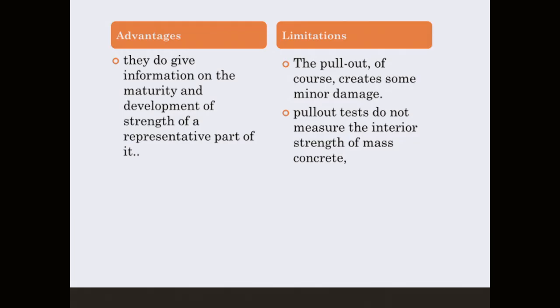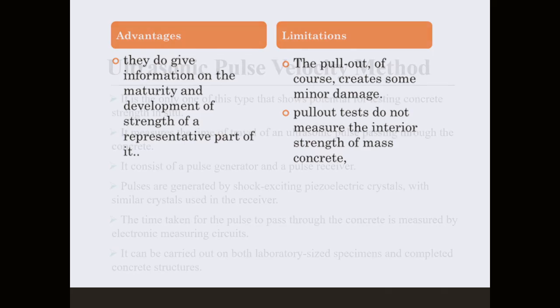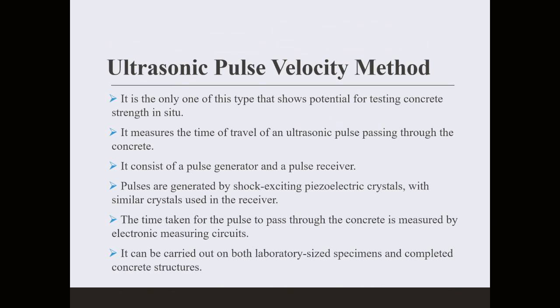Limitations: it creates minor damage. That's why I'm saying it's borderline. You cannot call it 100% non-destructive testing. But the advantage is it gives you a lot of information, even about the maturity. You can use it for relatively fresh concrete that was recently poured.